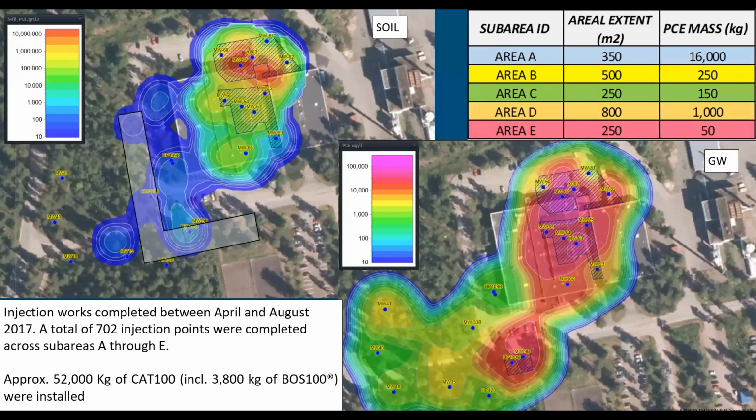And a final case study is a full, let's say, complex site where we started with a chlorinated plume that, despite the excavation and removal of PCE tanks, had been causing the client troubles for 10, 15 years. They tried to install a pump and treat between the building and the site boundary to control that plume, but they just couldn't handle the issue. When we came in with the high resolution remedial design, we actually found out that there was a large pool of DNAPL that had never been discovered, and that is what led the final strategy of the remediation.